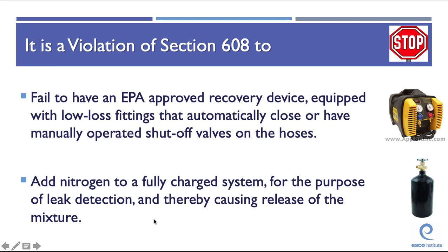It is a violation of Section 608 to add nitrogen to a fully charged system for the purpose of leak detection and thereby causing release in the mixture. As we talk about leak detection, you're allowed to use a little bit of refrigerant mixed with nitrogen for the purpose of leak detection with electronic leak detectors. However, you cannot add nitrogen to a fully charged system because you will not be able to recover that refrigerant and you'll have to release the entire thing into the air.